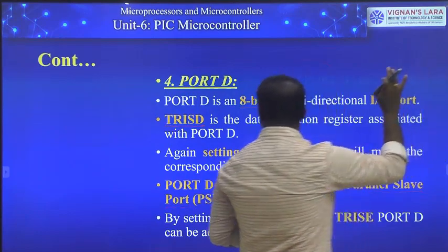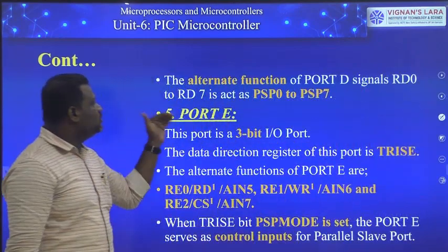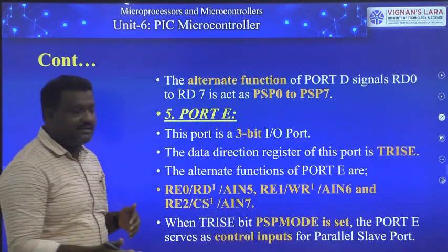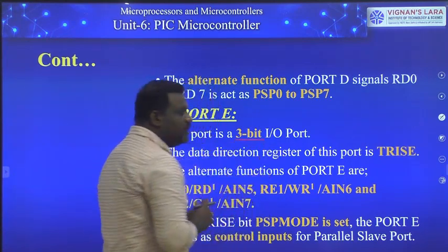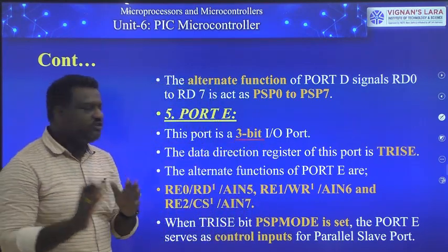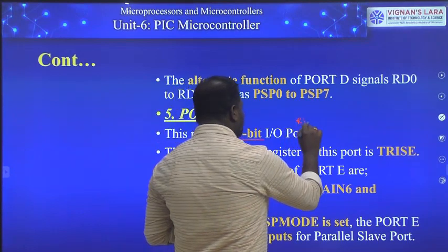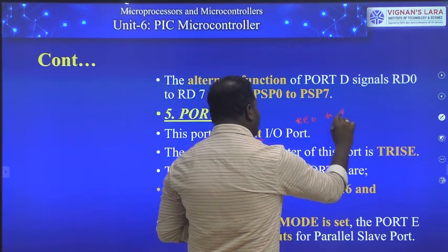And coming to the next, that is about port E. Port E size is a 3-bit I/O port. I already told you. It has only 3 pins. That is RE0, RE1, RE2.